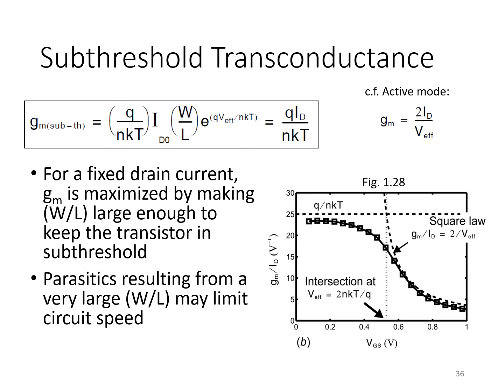According to the exponential voltage current relationship, if we take the derivative of that, it ends up looking just like the relationship for the small signal transconductance of a BJT. You get an expression like this, where you've got the bias current in the numerator, and a term here, KT over Q, that looks just like the thermal voltage.